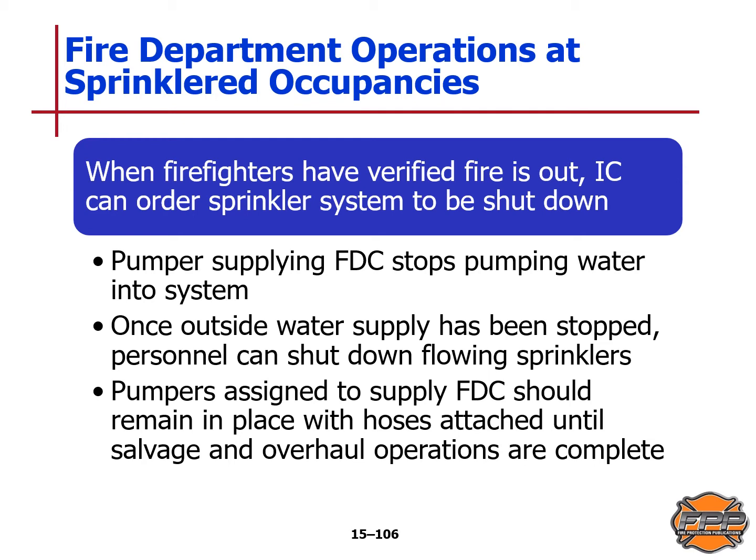The pumper supplying the FDC stops pumping water into the system. Once the outside water supply has been stopped, personnel can shut down flowing sprinklers. Pumpers assigned to the fire department connection should remain in place with hoses attached until salvage and overhaul operations are complete.